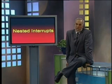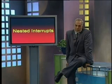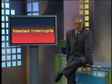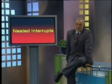One of the concepts could be that of nested interrupts. The concept in the case of nested interrupts is very simple. Interrupt service routine in itself is a program. We say that, well, if an interrupt service routine is being serviced, and in between another device asks for service or it initiates an interrupt, now, if that particular device has a higher priority or needs attention, then we can just save the environment within the presently running service routine and then give control to another service routine corresponding to a higher priority device. And after that service routine is finished, then we come back to the earlier service routine.